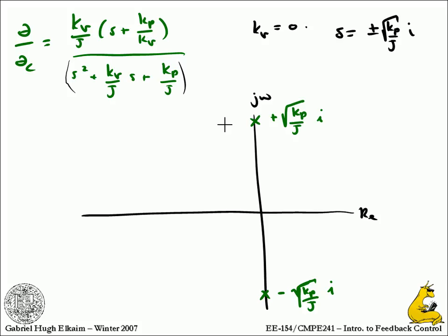So what happens as I increase Kv from here? Any idea what's going to happen as I start adding in Kv, the trajectory that the roots are going to take? We'll add a real component. They're going to be complex conjugates, but where are they going? They're not going to the left specifically. They're going to go along an arc down, because omega n doesn't change. If I don't change Kp, omega n squared is always the same. Therefore they are by definition along that radius. The only thing changing is zeta, which means I can move them down the semicircle.